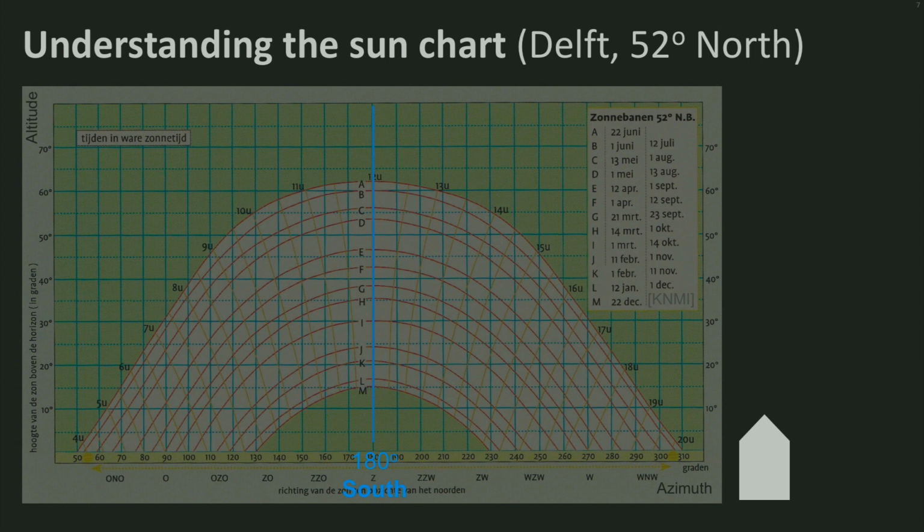Most people know that the sun course is described from east to west. This happens exactly around the 21st of March and the 21st of September, from an azimuth of 90 degrees off the north point, east, to 270 degrees, west. The sun reaches its summit at 38 degrees altitude, at midday, and if you look at the little house, you see that the insolation will be at this angle.